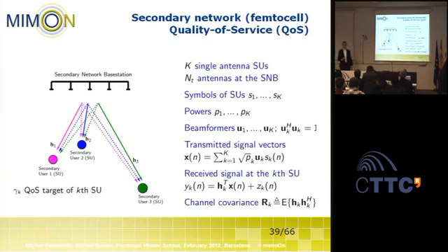So we assume that this channel vector is known at the transmitter, be it from feedback as illustrated before. So there's feedback between the receiver and the transmitter, or it could also be acquired from the uplink transmissions. So if we have a TDD system, time division duplexing system, so uplink and downlink are performed on the same frequency resource, then these channels can be estimated from the uplink transmission at the base station. So in the following, we will assume that we either know exactly the channels of the users, or we only know the statistics of these channels.